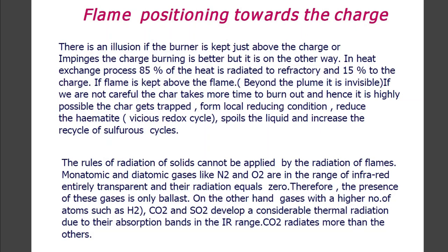Flame positioning towards the charge. There is an illusion that if the burner is kept just above the charge or impinges on the charge, burning is better, but it is the other way around. In the heat exchange process, 85% of the heat is radiated to the refractory and 15% to the charge. If the flame is kept above the charge, beyond the plume, it is invisible.